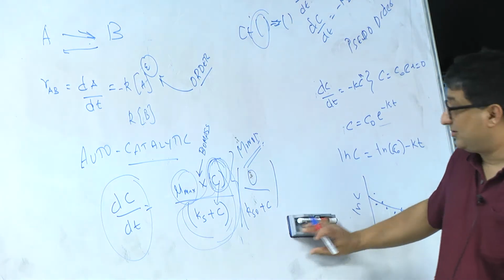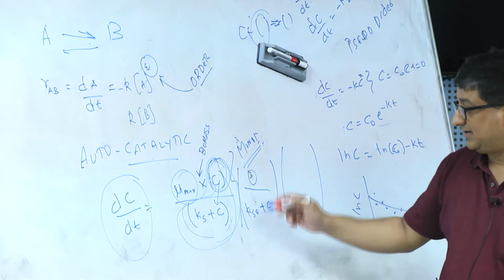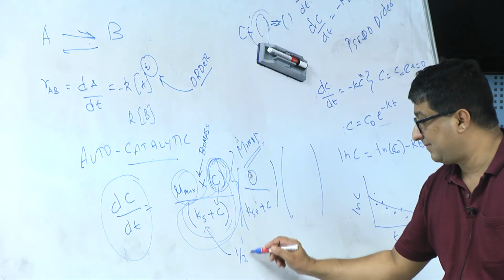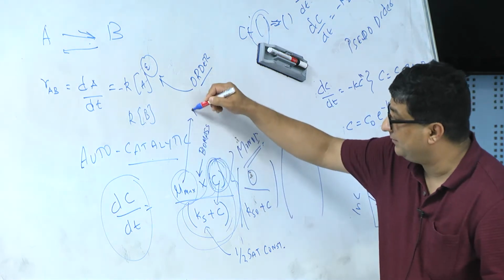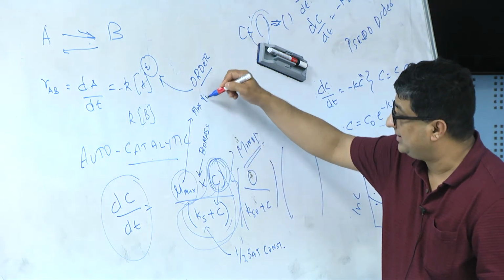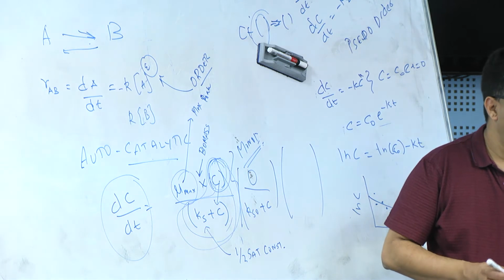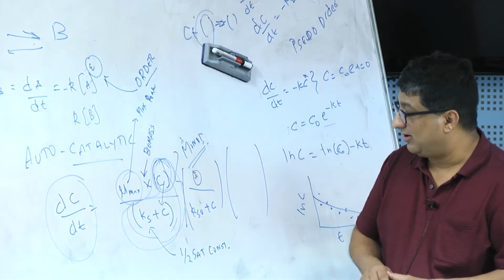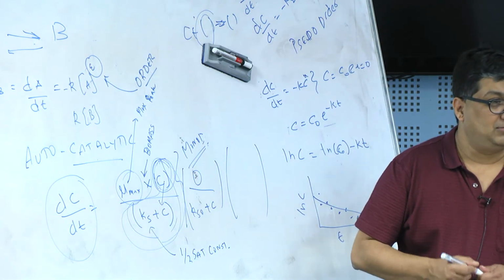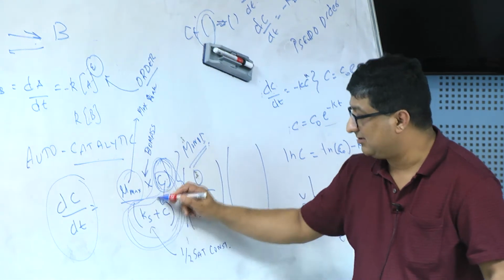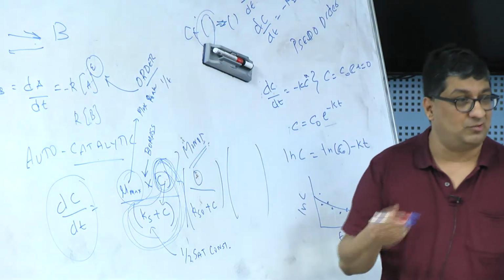So whenever there is a limitation, you put a multiplication of it and add a term that looks like this. This is called the half saturation constant, and this is called the maximum rate, or maximum reaction rate. The only downside is if I want to track substrates, there is C here, but this C goes away with this C, so that's dimensionless. Mu max has dimensions of 1 per time, just like a first order reaction.